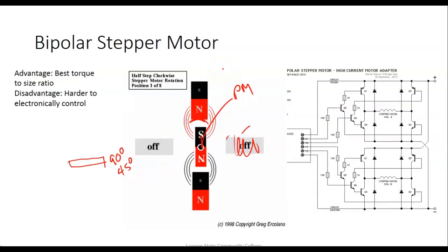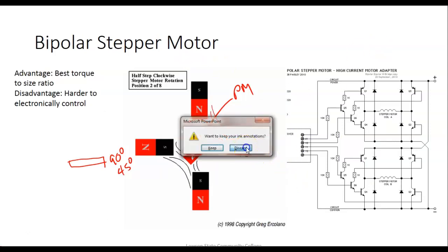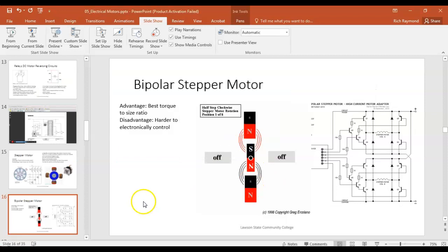So if we look at the carousel, it's got stepper motors. If we run them open loop, of course robots, if they use stepping motors, those guys are so precise, they actually have encoders on them. So you have 2 backups. Most of our stepping motors we run open loop but we start them from a known position, right? And if we start them from a known position, and then I step it 100 times, that might be 45, and it will go 45 degrees. If I stepped it 200 steps, then it would go 90 degrees, right?